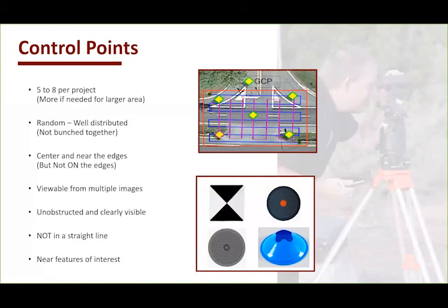Yeah, Paul, if I may, I just want to add one thing. I deal with a lot of smaller departments, and really they're interested in taking one aerial image and bringing that in with their measurements. And I did see a couple chats come across with, what could we use for control points? And I think, Dave, you'll probably agree with this, but you don't really want to use a control point that's too high because you'll get a perspective issue. Would you like to get into that?